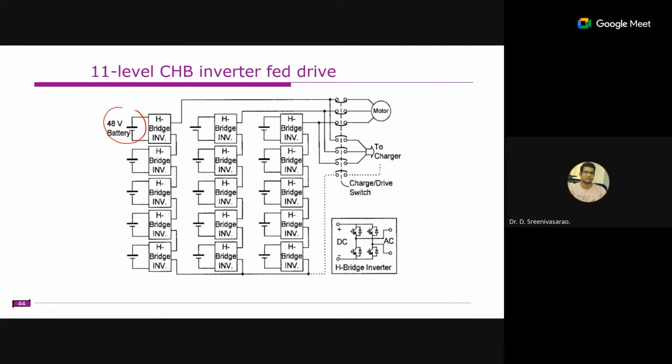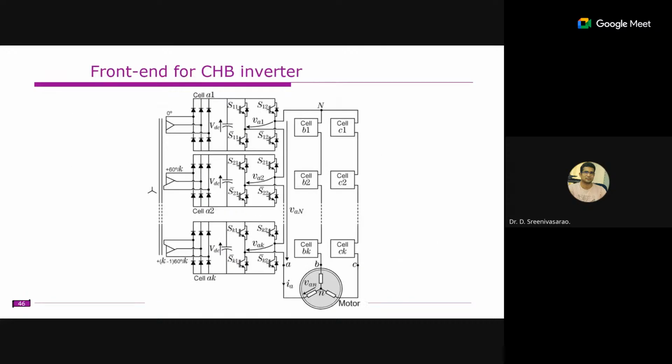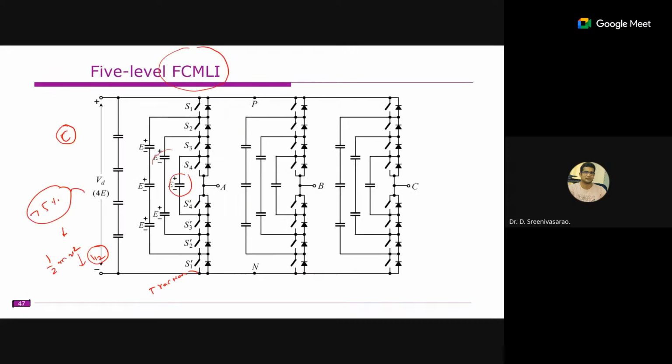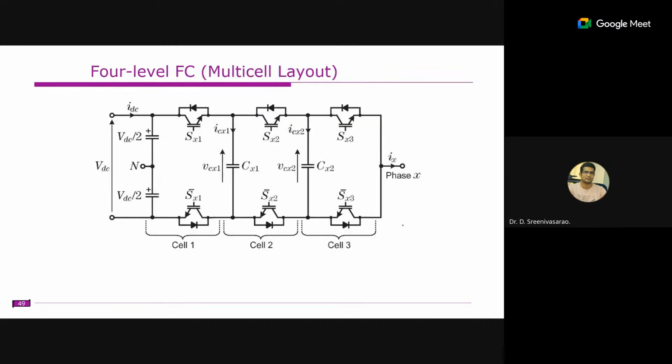So we have a lot of techniques like inter-SOC balancing and intra-SOC balancing. These are slightly complex things. Also there is active cell balancing. For example, if one battery has excess charge, somehow we transfer this excess charge into some other batteries. Right. That is not exactly a drawback, but one complexity that we need to address.